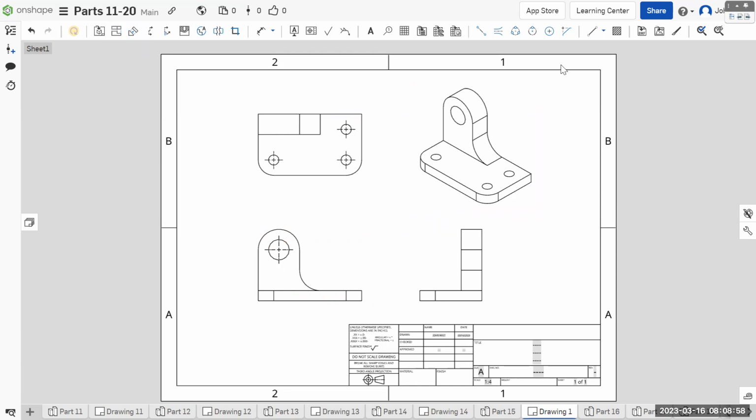Okay, so we have some curved surfaces, so we need center marks. They've already given us center marks for these tiny holes looking straight down, and a center mark for here. The only other curved surfaces are these front radii, rounded over edges. And we have this rounded over edge, and then we have this rounded over, but interior. That's it for rounded over. And oh, I forgot to do hidden lines, and that'll give us one more thing. Show hide shaded.